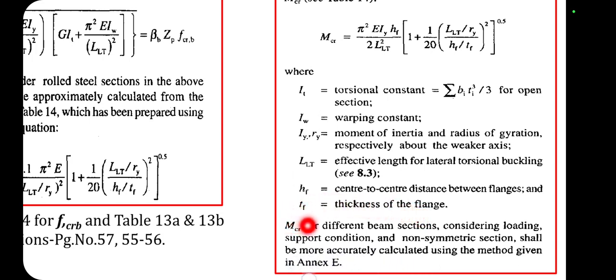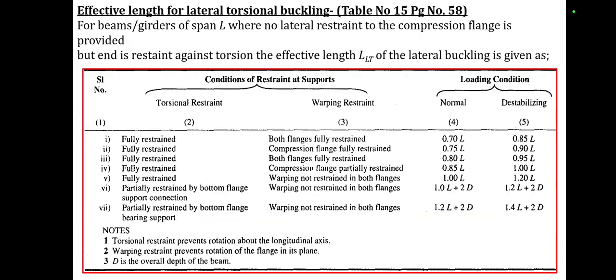Hence, Mcr for the different beam sections, considering the loading, support conditions and non-symmetric section, shall be calculated more accurately using the method given in Annexure E.